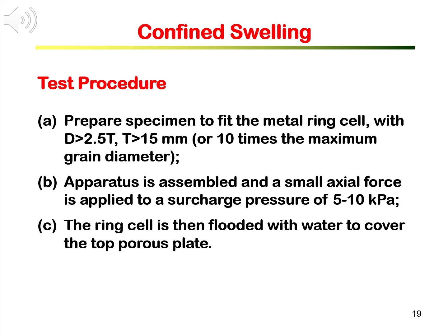Specimen should have diameter at least 38 mm. Most likely, specimens are cut from rock cores, and therefore its diameter D is around 50 mm.